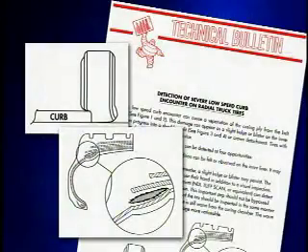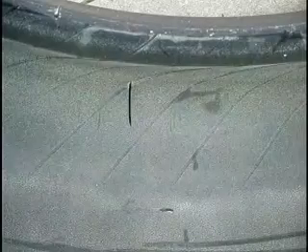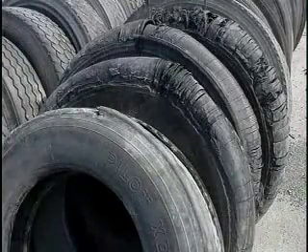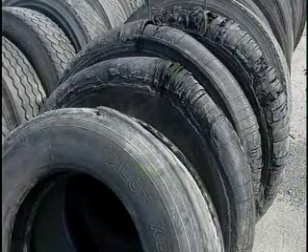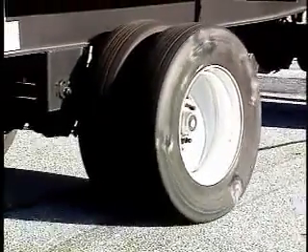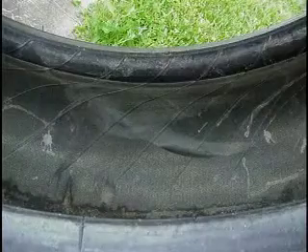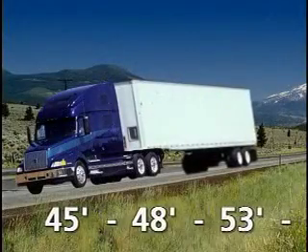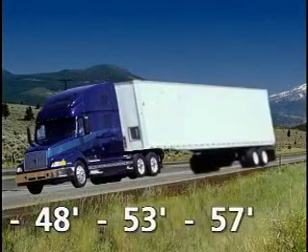In addition, there can be internal damage to the tire, such as a tearing of the rubber products between the carcass and crown plies, as well as the creation of a radial split condition. Both conditions, without careful inspection, could be overlooked and create a separation later in the tire's life. Pinch shock damages are primarily seen as trailer tire damage. However, all wheel positions on a vehicle have the potential to experience a pinch shock condition. As the length of trailers increase, so does the potential for this type of damage.